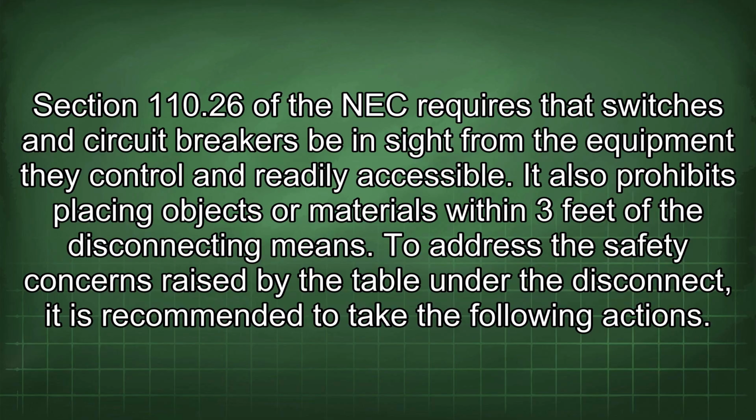Section 110.26 of the NEC requires that switches and circuit breakers be in sight from the equipment they control and readily accessible. It also prohibits placing objects or materials within 3 feet of the disconnecting means. To address the safety concerns raised by the table under the disconnect, it is recommended to take the following actions.